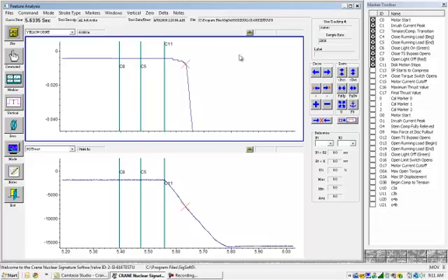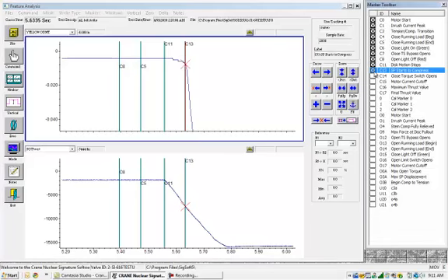Again, that's up for interpretation, but look at the amount of load we have. So it takes a substantial load to really start compressing the spring pack. I got a feeling this little amount here is gap coming out before the spring pack starts to fully compress.